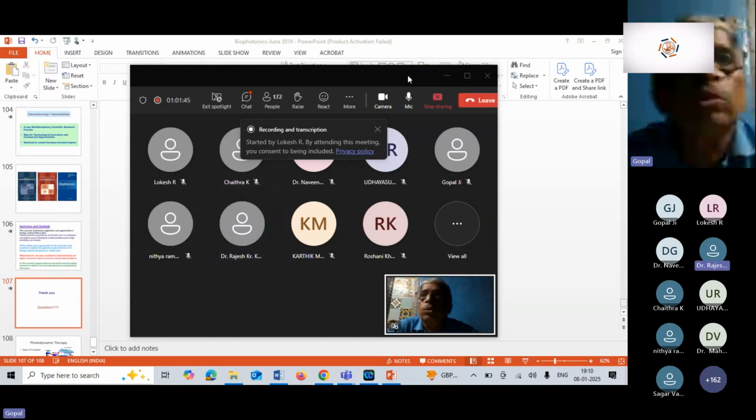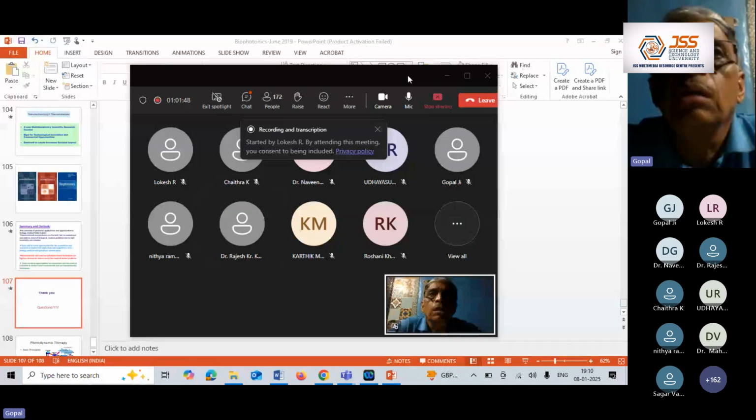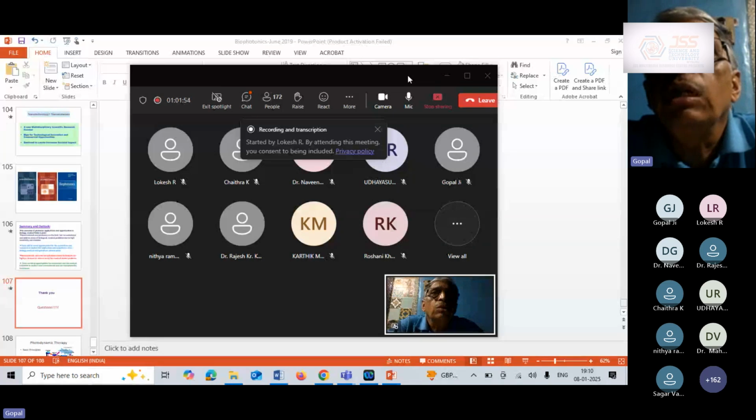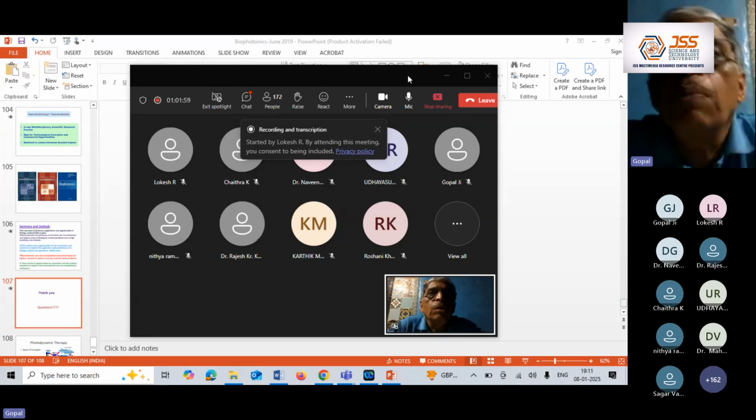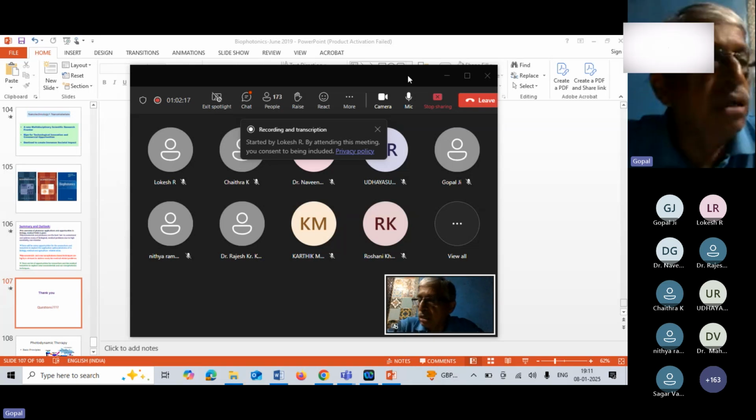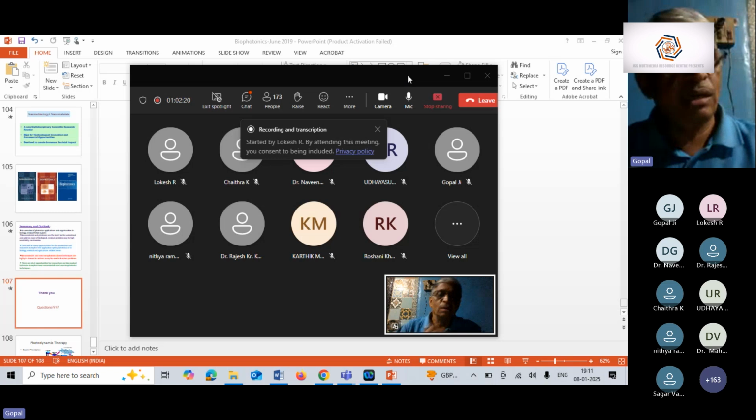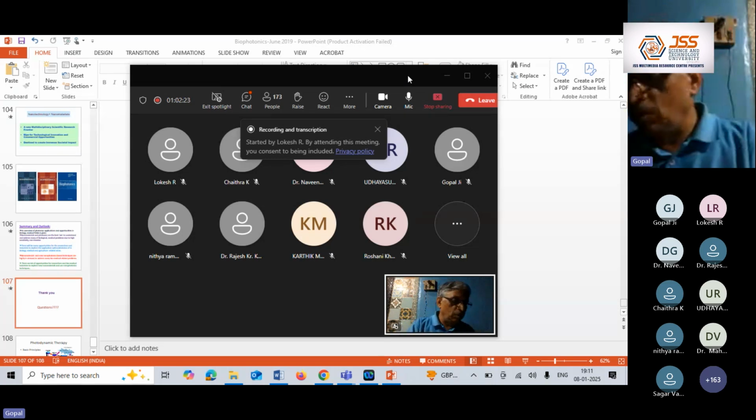It goes with the selection of the material and the type of application. For detection or sensing, maybe you can use simple biocompatible material, normally polymers and these kinds of things. Among metals, gold and silver don't create any problems. For therapy and other kinds of treatment, you have to look into the biostability of the material. That is very important, because it may react or it may cause other tissue related problems.